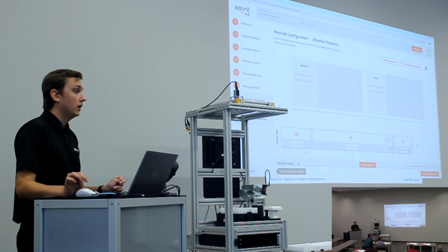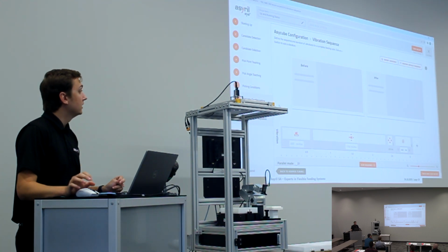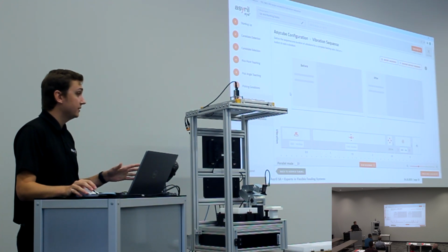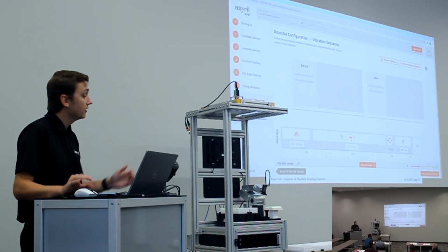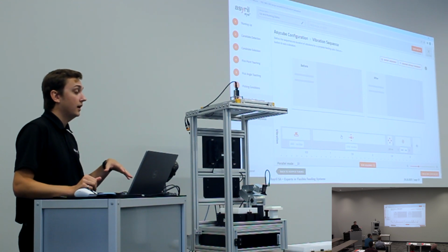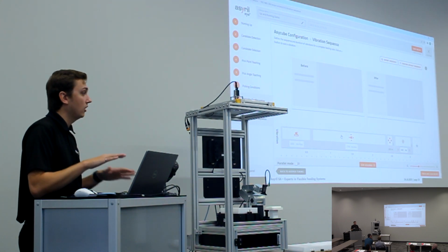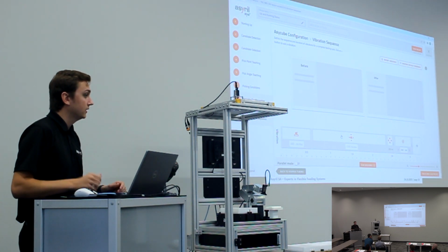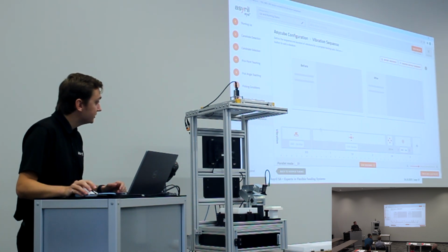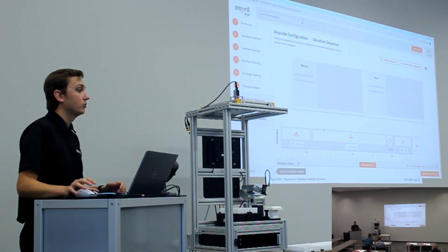When you are programming a robot with I+, super easy, and the typical command you call is get part. And when I+ receives get part, it automatically takes an image, determines the center of mass of these parts, and uses the smart centering, if you've got that in your sequence here, smart feeding to fill in how many parts you need on the hopper, take an image, and send a part coordinate back, all automatically. The only programming that you need to do is actually call an I+ function, get part. And so that vibration sequence here is what's performed when you call get part.